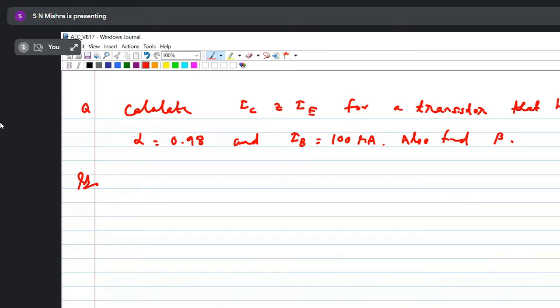Here you could see I have used one circulator, that is C2, and here I have a fiber Bragg grating, which is blocking lambda 2. So when this lambda 2 is circulated to port 2 of circulator 2, it will be given as input, and when it passes through this fiber Bragg grating.